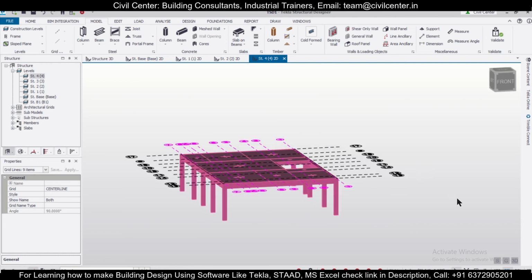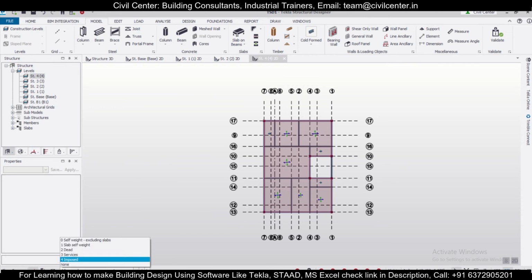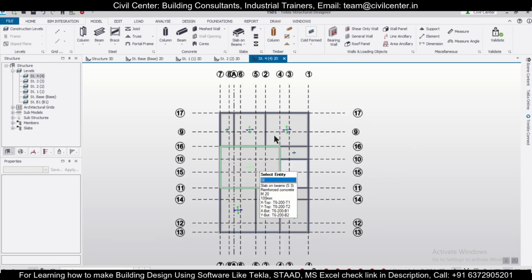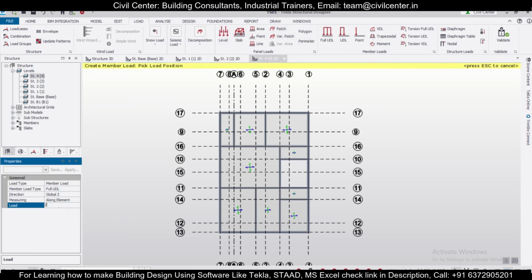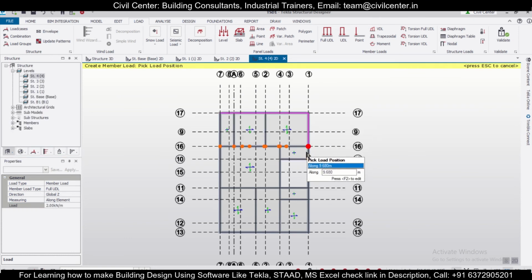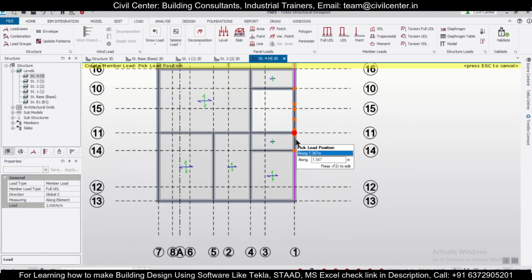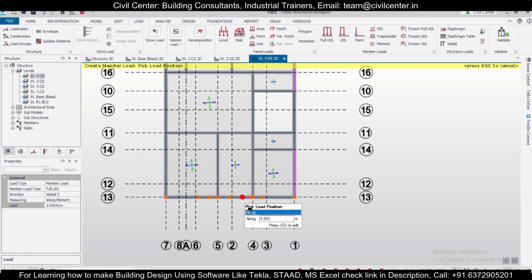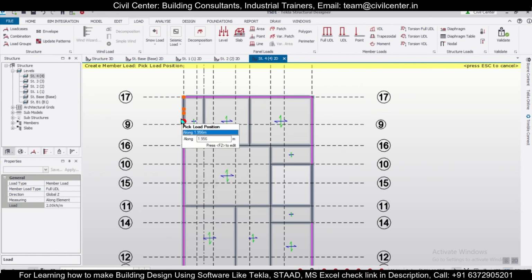After the loads are deleted, we can go to this imposed load. We have already assigned the same, so don't need to worry about that. The dead load we'll change here. So we'll go to this particular option of loading, this full UDL 2 kilonewton, and give it for the terrace portion, 2 kilonewton here, along here, along this small span as well, and along this span. So this span we need to take care of. This span, this, this and this.